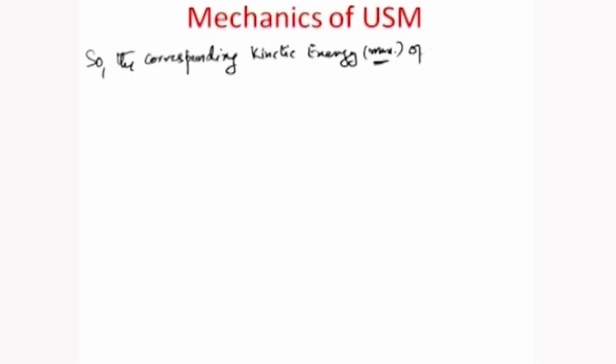Okay. So therefore the maximum kinetic energy of the abrasive grain, I already explained to you before that it really is nothing but the maximum velocity of the tool. The inertial component of its own self of the grain is so small that we do not really treat that in this equation, and so therefore the maximum kinetic energy of the abrasive grain is given by the term half m v square, right,